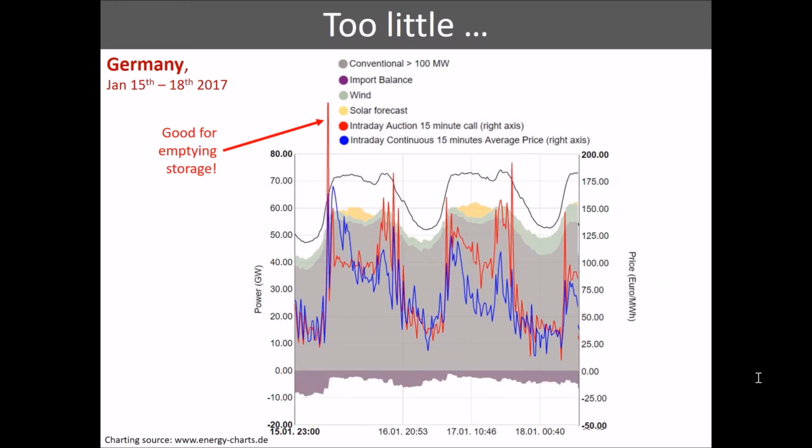We've got time of high demand, we've got very little wind, so what we've had to do is turn up more of our conventional plants, and in particular we've had to turn up some of our peaking plants, which are going to be very expensive to run, and also because in the previous chart, and other times when we've got lots of renewables in the system, which we take first, they're not being required to run. When we call them up, they know that they're a last resort, so the prices tend to go very high. So that's two examples within a short period of time where lack of flexibility has caused economic issues, so negative pricing and real spikes in peak pricing.